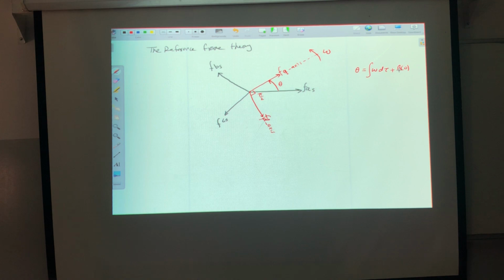Same as Laplace. We are solving in Laplace. In the end of the day, I need what? Laplace inverse. If I cannot find Laplace inverse, it will be useless. Because solving the problem in the S domain, we never solve the problem in the time domain, unless you have the way to go back to the physical system, the physical coordinate. So I need a transformation that I can go from ABC to DQ or QD, whatever, and I need to return back. And I need to preserve the power. Otherwise, I'm changing the system.